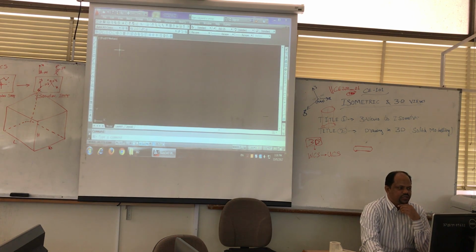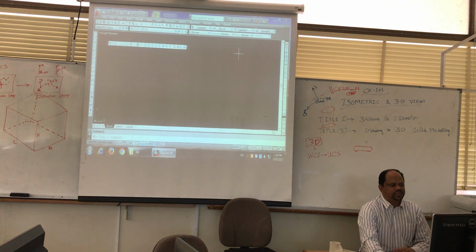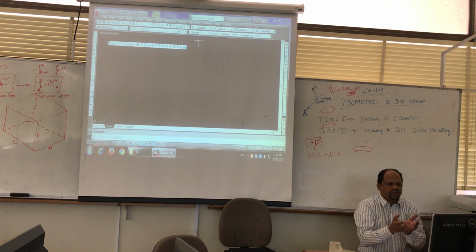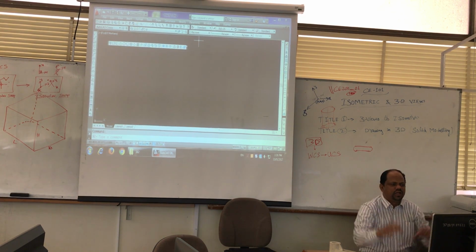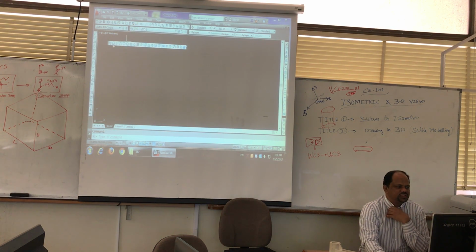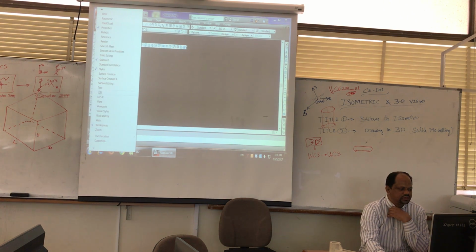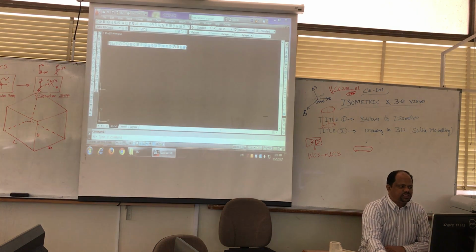Modeling. In the side menus, we can turn toolbars on and off anytime, because if we load all the menus, the screen will get filled with them. It will occupy memory also. So we keep them off, and when we want to use one, we open it. So this is the AutoCAD modeling and editing command toolbar. Fine. There is one more command that I would like to use, which is UCS. Go down here with the arrow. Can you see UCS? This is UCS, 2 and 1. Just use UCS; UCS 2 is more advanced. You see, these are the commands of UCS. It has loaded here. So these 2 you have to load. I will close it again.